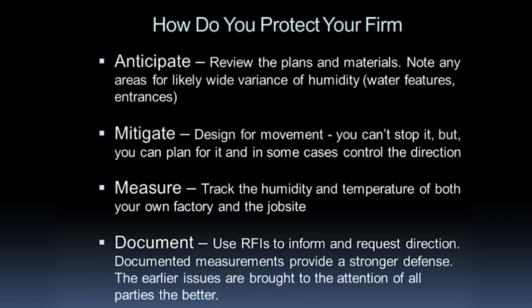One other thing I should have mentioned in measuring, I would strongly recommend that you also check the materials as they're coming in. Because during my time in the industry when I was running a company, we ran into a situation where our supplier was bringing us material that was nowhere near the moisture content we had expected. And it took tracking it and letting them know we were tracking it and rejecting it before they finally got back in line and started bringing it in where it was supposed to be.